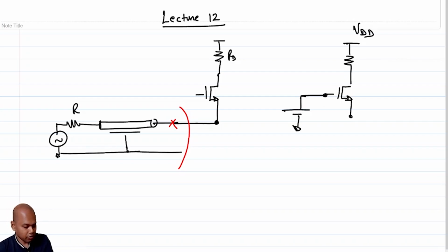The quiescent voltage at that point is essentially zero, because we are connecting everything to the antenna, and this is mimicking a sinusoidal source which has a zero DC level. So if there is no DC connected anywhere on the part of the circuit on the left, then it is at a zero quiescent point.